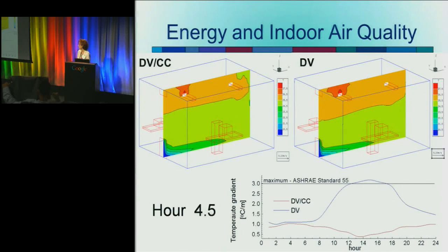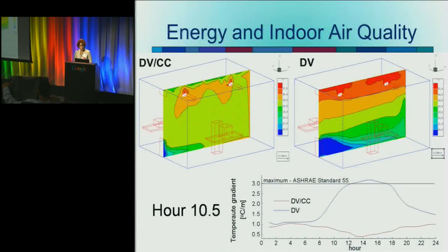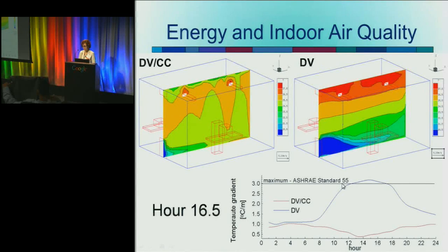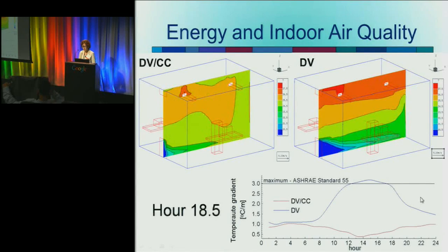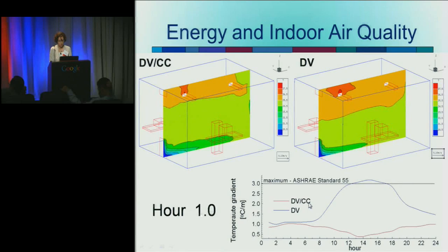And we can see how the temperature changes throughout the day. And I can decide which system will work better for me in this particular space as a building owner. And we can look also here, there are some standards that approximate how human occupants perceive that space. And we can see that displacement ventilation versus this other displacement, the chill ceiling ventilation, had a different temperature stratification from your ankle to your head.